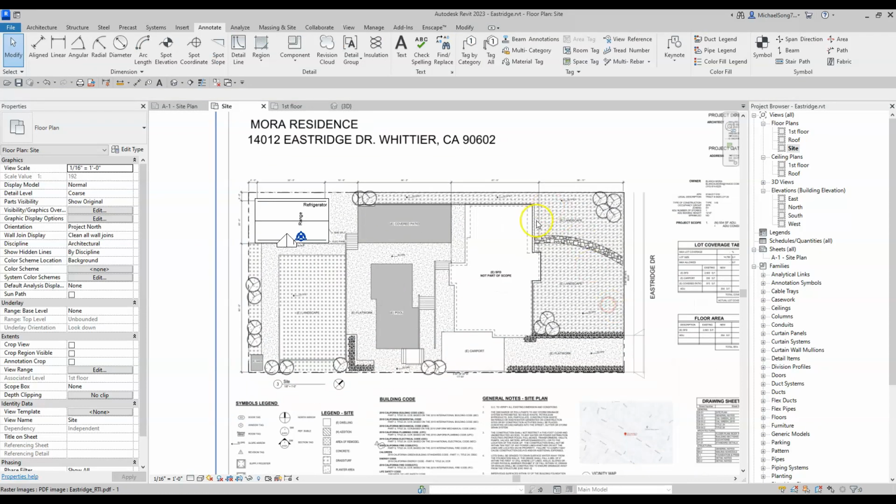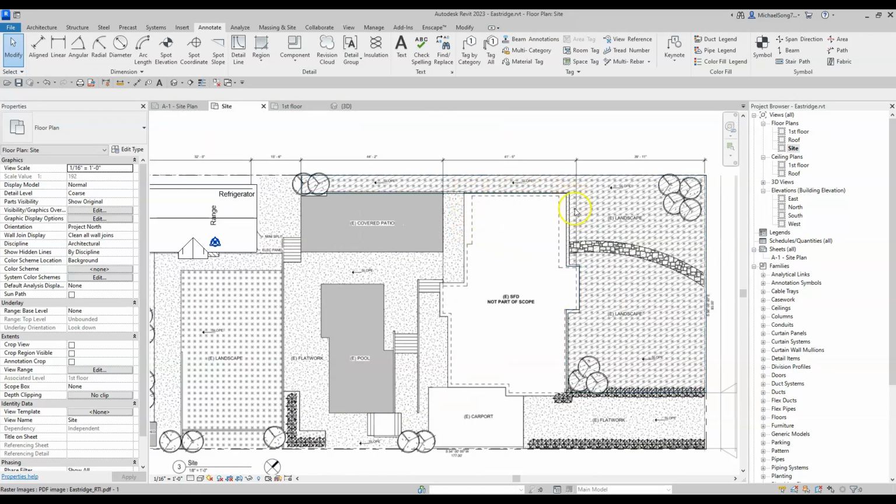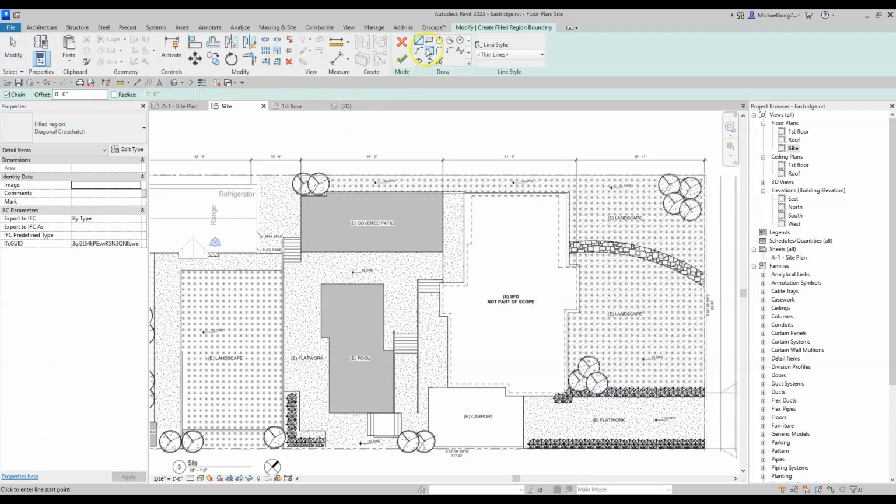Okay, so that's how you create the hatch. This is just going to be a white hatch, but this will be a good example. Let me do a concrete real quick. Hatches are not too picky, so you can overlap things. So let's just cheat, and let's just do a really poor job of getting this border.